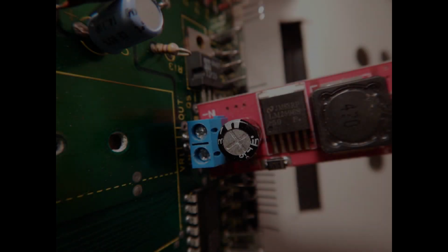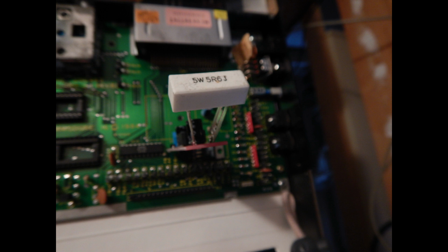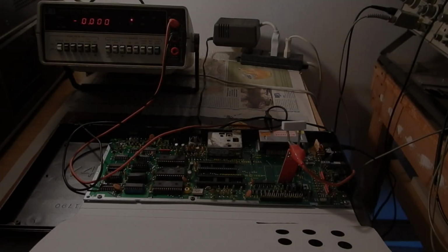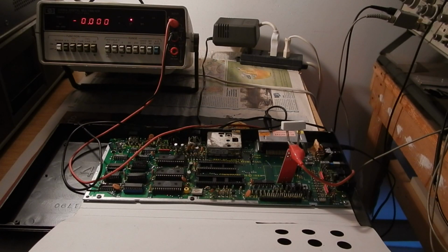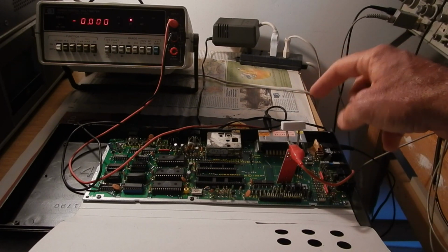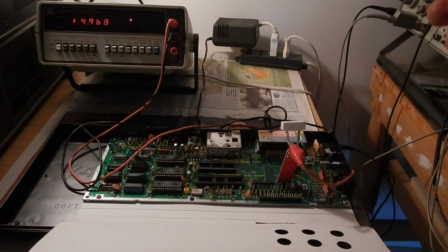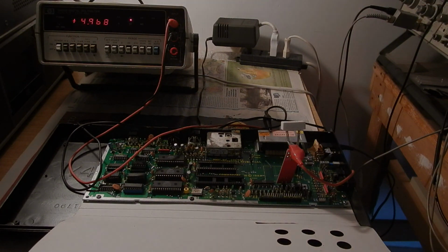I decided to test the regulator directly with the voltage input from the C16 board. And of course, initially, the output will go only to the load resistor. The first test is obviously just checking the output voltage with the dummy load. And it's close enough. Well, almost perfect. 4.97 volts.